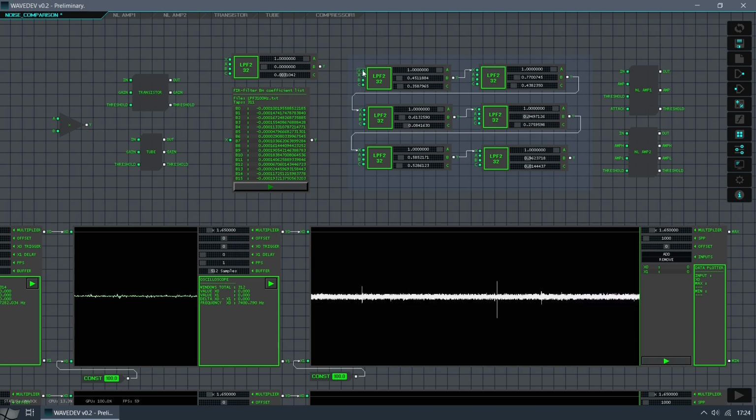That explains why you can't get rid of noise with digital filters. Noise is also information that is embedded into the signal. Therefore you can transform it, but not eliminate it. This forces us to have to remove it before the conversion. The only way to create or destroy components from a signal is by distorting it. But that brings consequences that can be intolerable. Anyway, this gives rise to a broad debate about which I will speak a little more in the document. Now we are ready to move on to the last stage of our distortion.